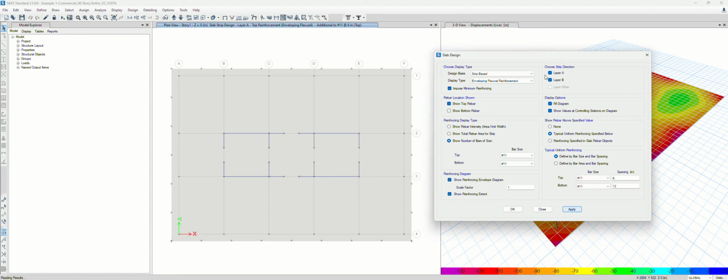So you could do the same in the Y direction as well. Obviously, in the Y direction, again, you have more overturning moment due to the wind loads, right? And then it has more significant bending. Obviously, bar design is based upon your maximum bending moment. So you could just see and choose. So you just play around with this.